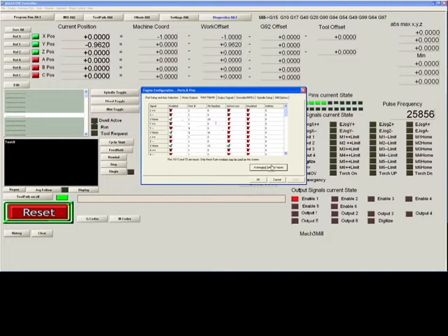Even if you use automated setup of inputs, you should take a look and see what it did so that you understand what active low does. It's important for every user to understand the effects of active low. It either toggles the state of the input that is seen as active, or it toggles the state of the output if it's an output signal.